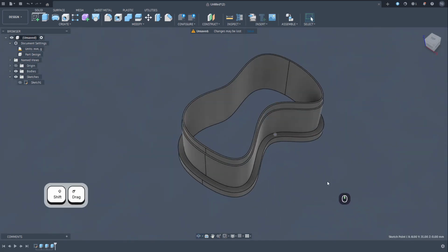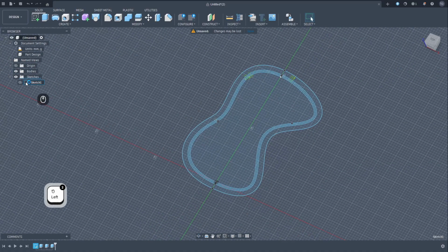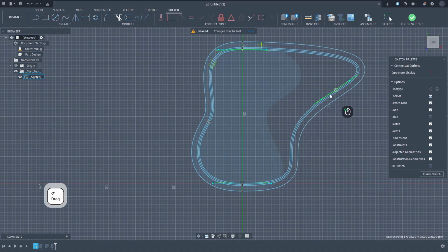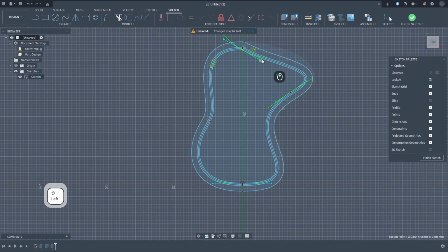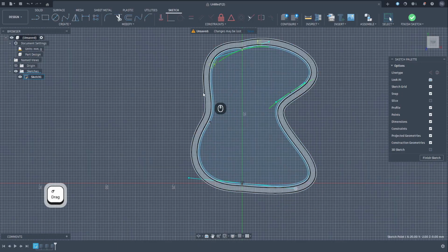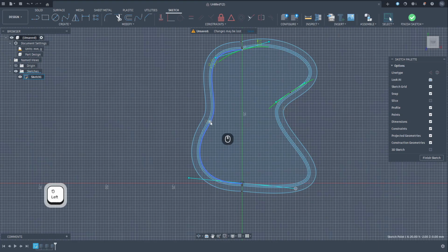And let's say if you look at something and it's not exactly how you like, just simply go back to your sketch and modify whatever you want and whatever you need, and it will modify your object. Now, because you use mirror, it won't use both of them. You're gonna have to go and modify every one of them if you want to create a different one.